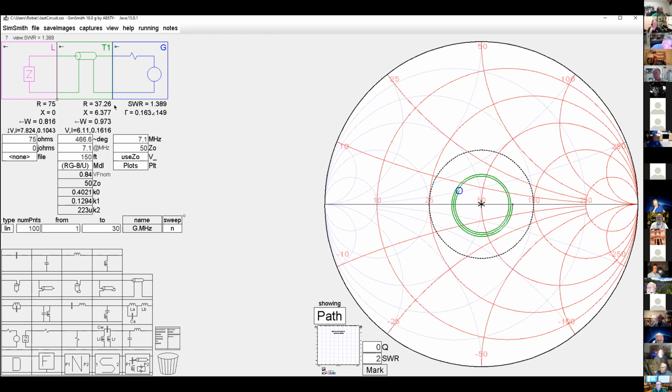So Robbie, question. Sir. Mark, N5PRD. Yes, sir. So this is really saying that the SWR is most appropriately taken at the antenna and not at the feed point. That is correct. Thank you. Well, not really. Not if you have SimSmith. You can take it anywhere you want to. You just apply it in SimSmith and you can find out what it is at the antenna. But the concept is, what really determines SWR? The characteristic impedance of the transmission line versus the load at the antenna. That's really what the figure is. The other things that you measure are of some significance, are indicative, but they're not the true number unless you go through some analysis like this to tell you what the real numbers are.